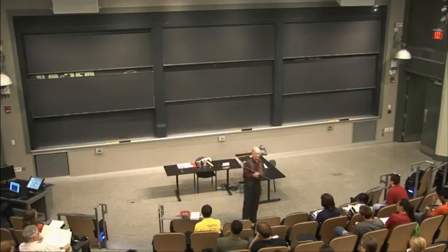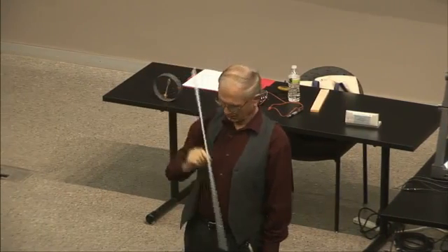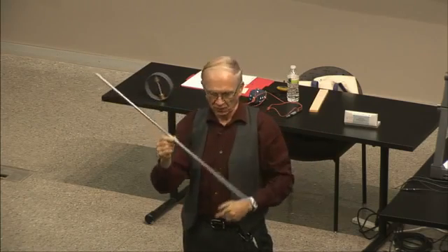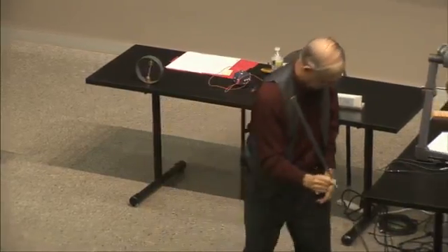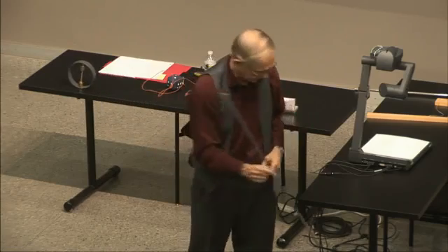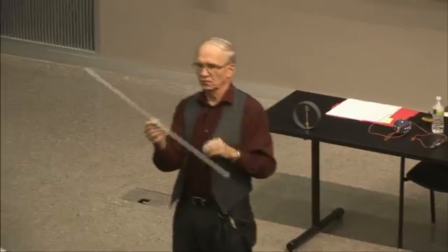But now I'm going to excite one mode of vibration of this. Hear the real high pitch? Get it down here by the mic so the people at home can hear it. About 1 kilohertz, way up there. And that's one natural mode of this thing in longitudinal vibration. When I thump it sideways, you hear a lower tone. Hear that? That's bending vibration of this thing. But each mode of vibration I can think of in terms of its equivalent single degree of freedom oscillator.